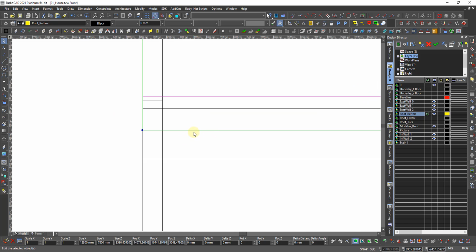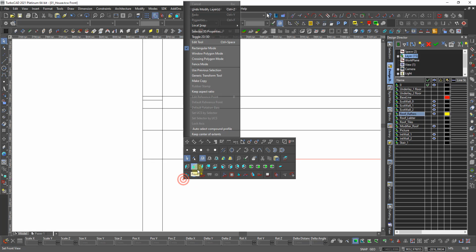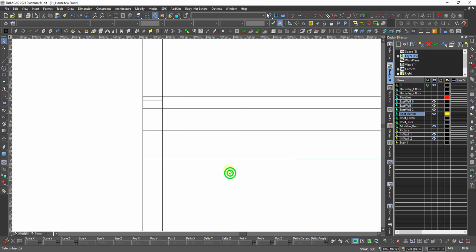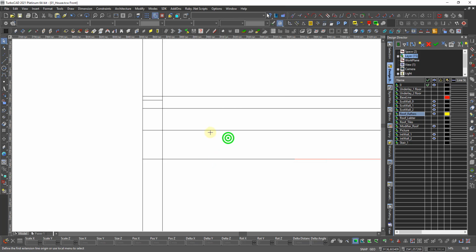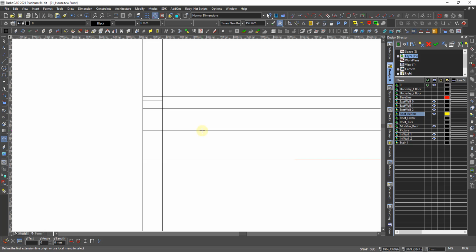So there should be 220 from there and down. I hope that is correct, because else there's a much bigger job to adjust. So we see we have this, and I want to measure from nearest to nearest, and there's 220, and that's good. Then we know the rafters stay in the correct position.